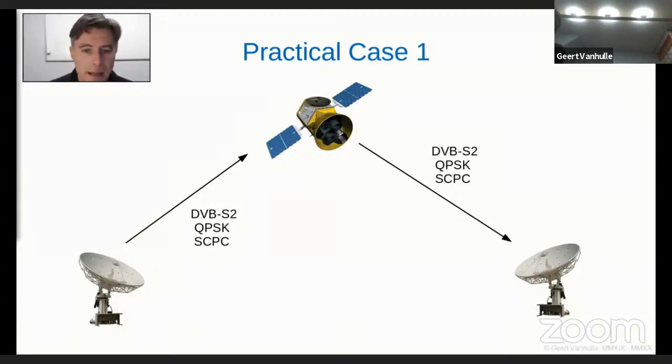This is the situation that we have in the satellite world, mainly in geostationary satellites, but also on other types of satellites. And the fact that signals stay analog in the satellite doesn't mean that we are not transmitting digital signals over satellite. If I use this example of an SCPC, single channel per carrier, signal going up to the satellite, a digital signal using DVB-S2 and QPSK as modulation, it goes into a linear transponder, and the signal comes back just exactly the way we sent it up, and it goes to the receiver sites, when it's a contribution signal.